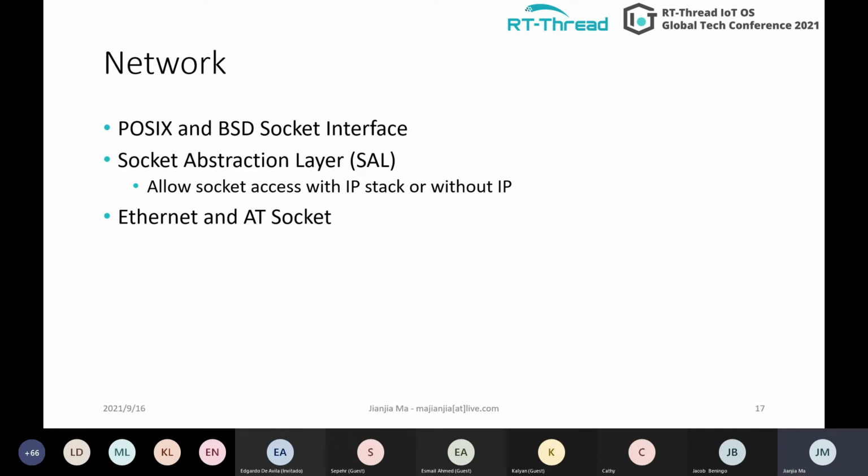Some low-cost platforms don't have it, and then you need to use IoT modules like ESP8266 and SIM800 to manage the internet connection. These modules normally have built-in IP management and socket management, so with that kind of module you don't need to run your IP stack. What the SAL does is unify the access to it. Therefore, we can use POSIX on it.